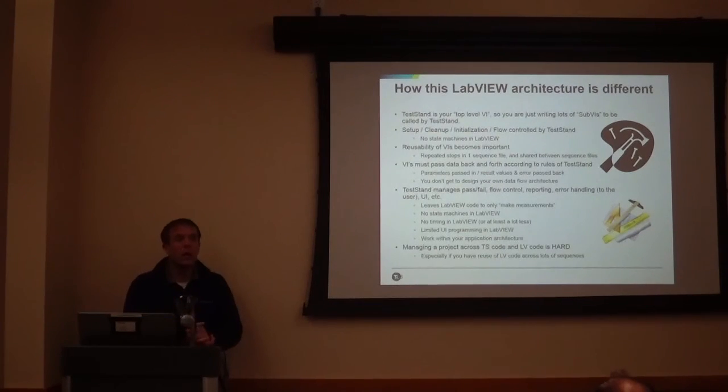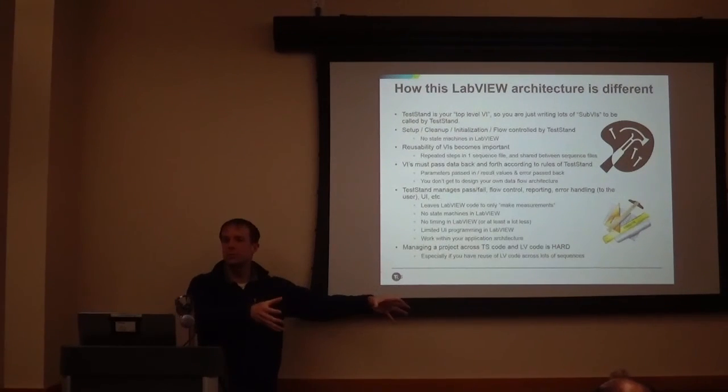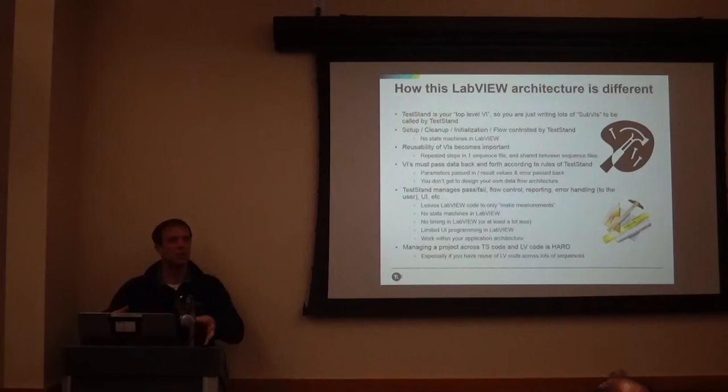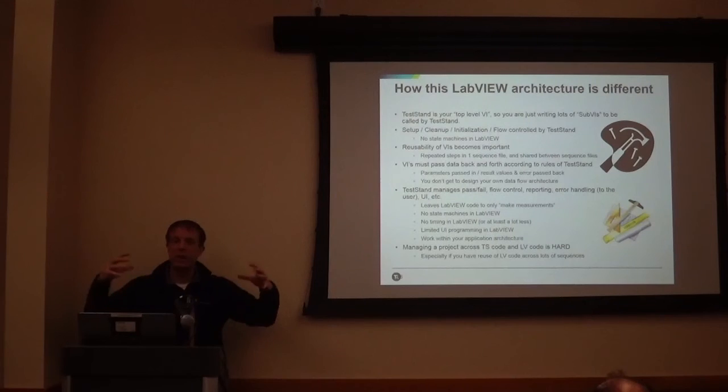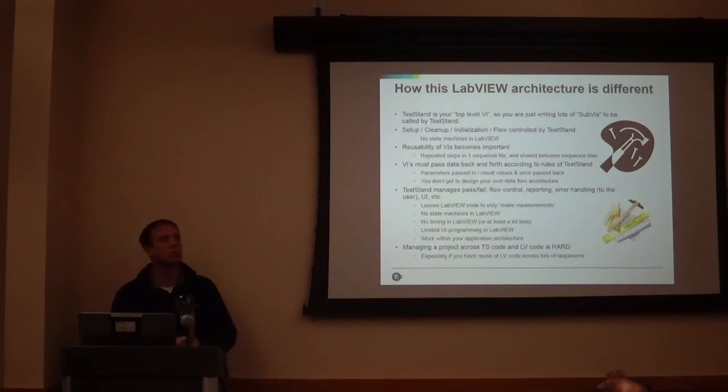So it really comes down to you have to really think in two spaces. I have my TestStand code that is doing my sequencing, and I have my LabVIEW code that's doing my measurements. And trying to think about it all as one entity and doing your project across your TestStand code and your LabVIEW code is very difficult. But if you can abstract out of, I'm just focusing on the LabVIEW code, I have a good model of what that VI has to do and trust that my sequencing and TestStand will behave itself, things become very manageable.